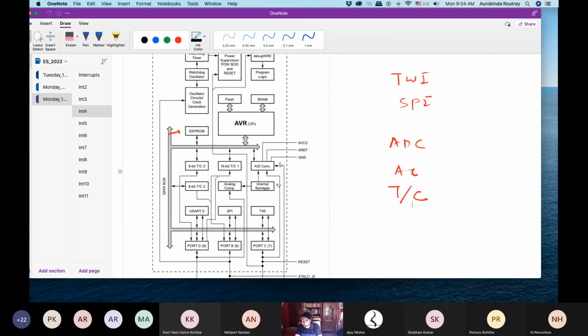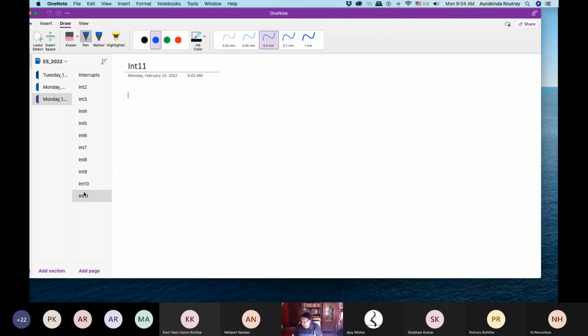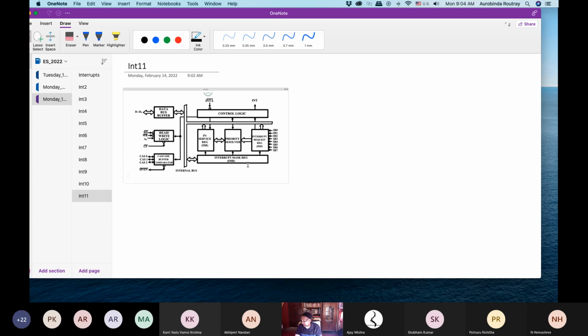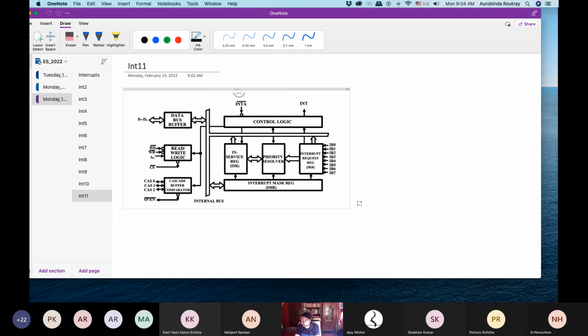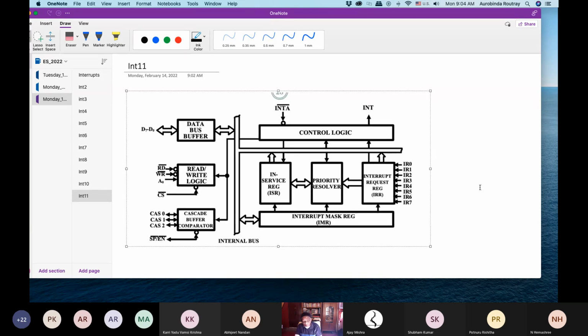If you look at this interrupt controller, what is the job of the interrupt controller? It brings in external interrupts and channels them to the processor, which has just one interrupt. Let me show you the internal architecture of this particular 8259, which is from Intel. I'm showing a generic architecture. This is a chip called 8259. This is a very famous chip. It is called a programmable interrupt controller. There may be other controllers.